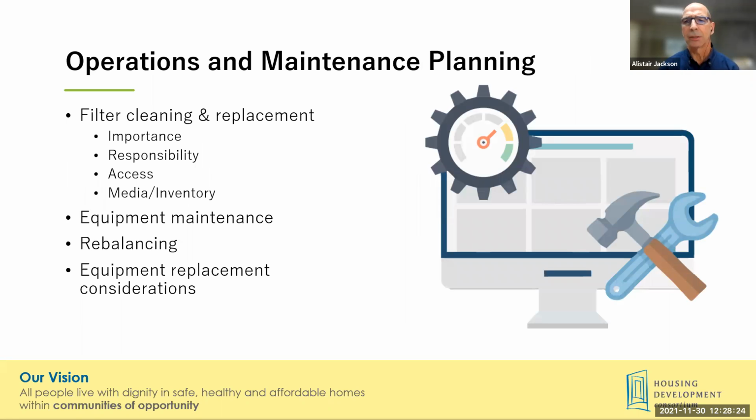As we've already mentioned, ERVs offer the potential for cleaner, healthier indoor air via high efficiency filtration. But those high efficiency filters need regular cleaning or replacement. If you opt for a distributed ventilation system, that's going to include a grease filter in the kitchen exhaust.